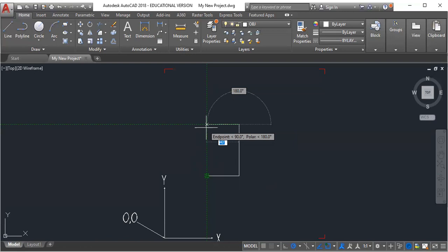And I can just come down here, and this is called a snap to that endpoint. So I only had to do my data entry, my keyboard work, on 2 different lines. And I still created this rectangle using lines, what I call going around the block. And then if I don't like that, I can always undo it and it goes away. I can redo, bring it back.